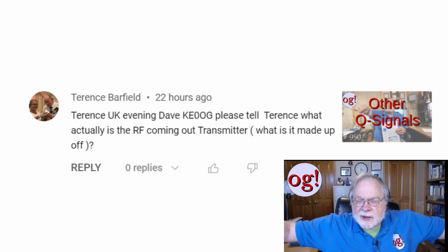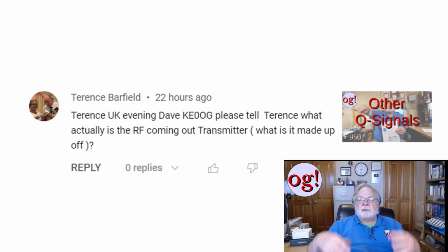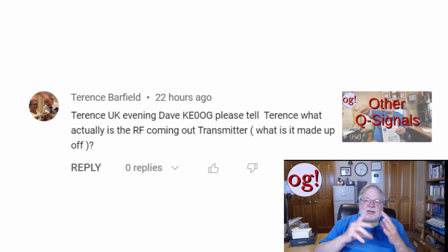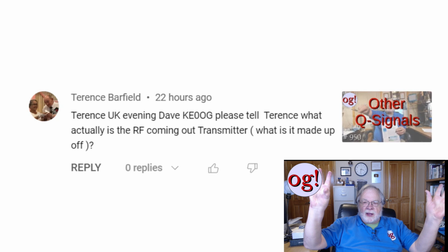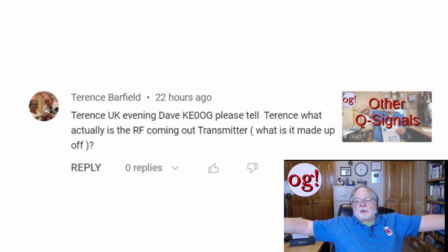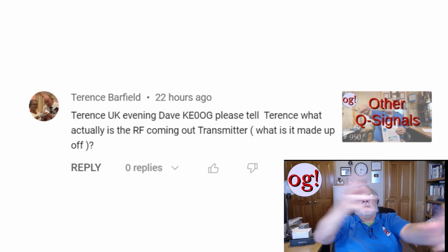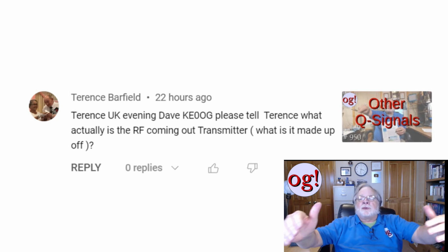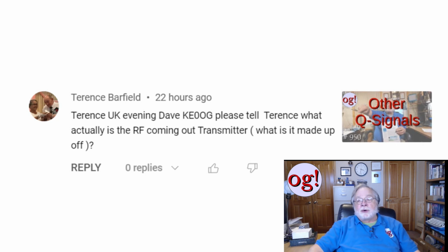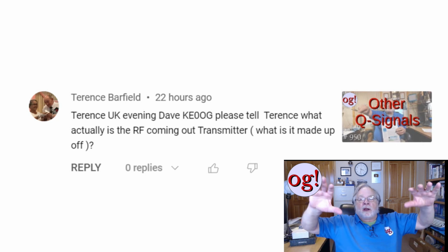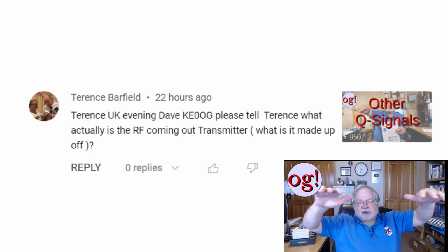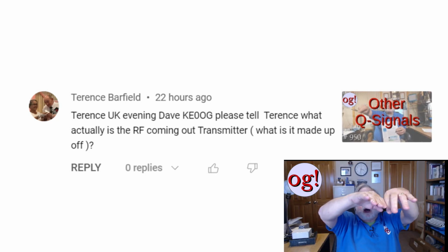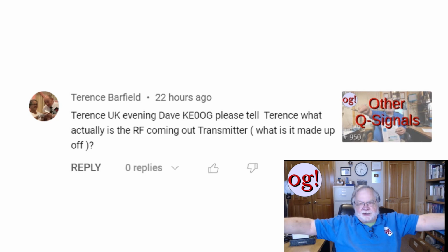Now, the antenna is spread out in such a way that each point on the antenna is like a little point that's radiating RF. And when you collect all those points together, they create a mess of RF. If you get a little further away from the antenna, about 1 or 2 wavelengths, all that mess superimposes on each other and creates a wave front.